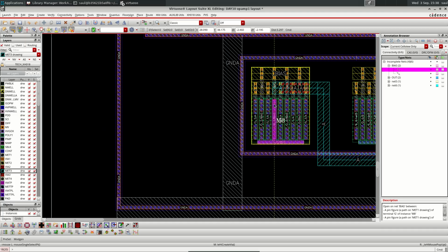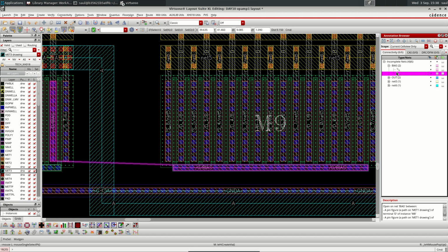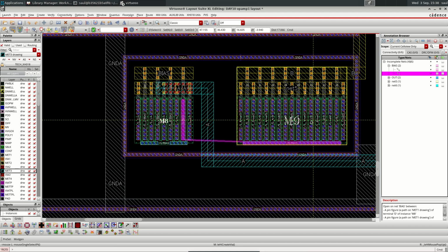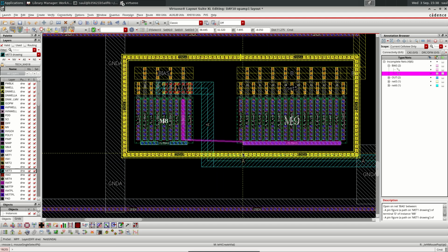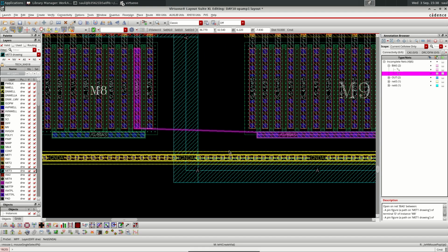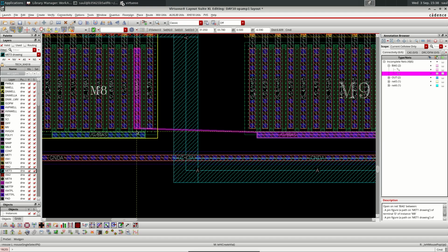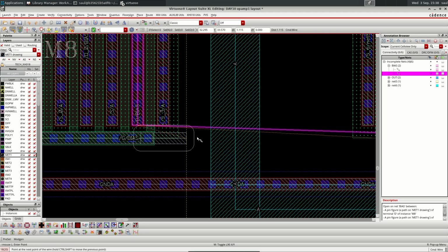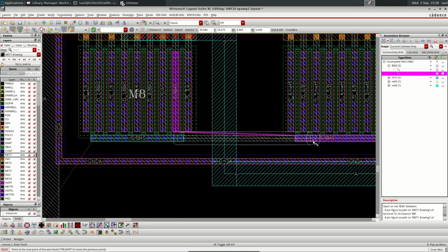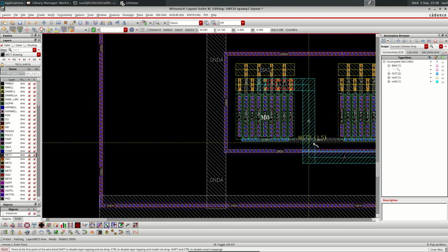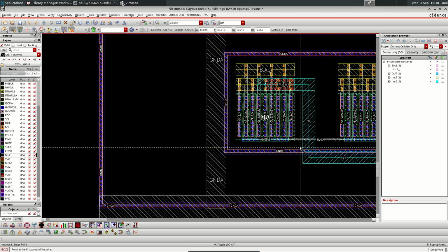It's telling me this transistor is not connected, and it has to be connected to here. So we can run a connection first from these two together. I disappeared one, and then I need to short these two. Okay, so this one is not carrying current, it is connected only to the gates, so I can keep it.